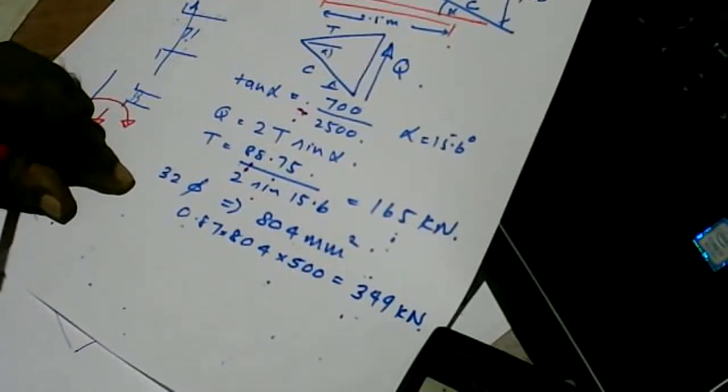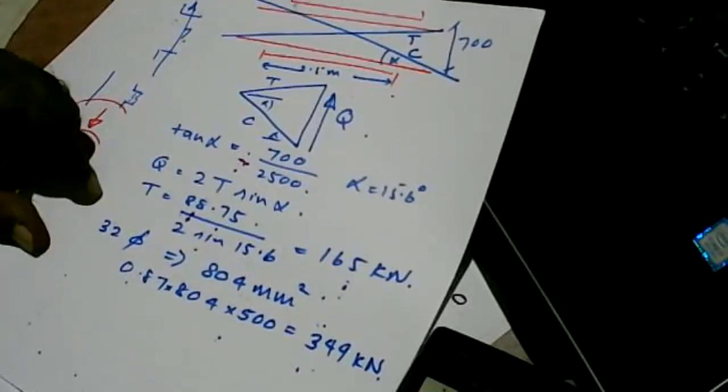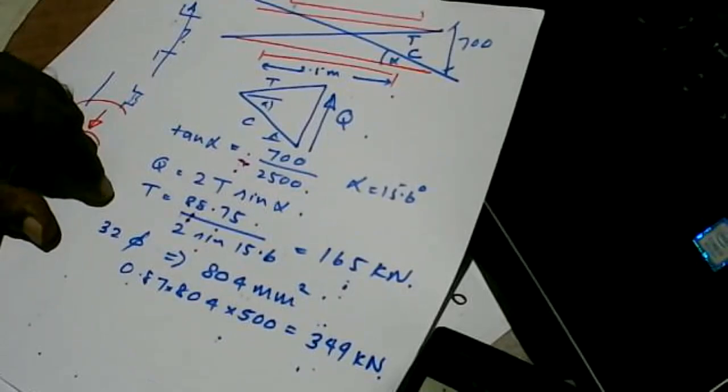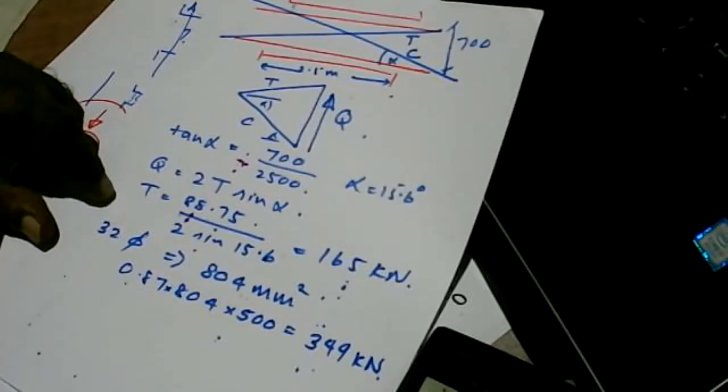So in case of an earthquake, because we have the normal reinforcement and the additional diagonal bars, this coupling beam will not fail easily. So we generally provide this diagonal reinforcement in coupling beams to prevent the shear failure that can lead to the formation of plastic hinges at the beam wall junction.